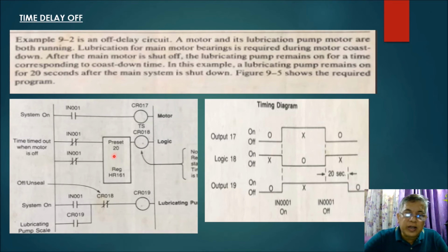For 20 seconds, this CR018 here will be energized. Okay? And if CR018 is energized, automatically the internal contact here, CR018, will open after 20 seconds.